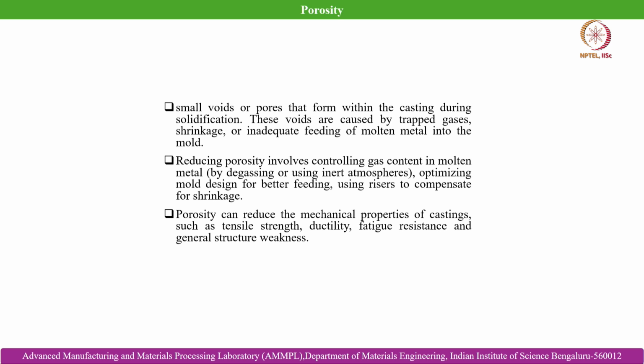So all the different kinds of defects that are generally generated in a cast part, largely concerned with porosity, can be alleviated or significantly brought down by effective design of the die cavity. Porosity can reduce the mechanical properties of a casting significantly. It also significantly decreases the density of the cast part, and thereby